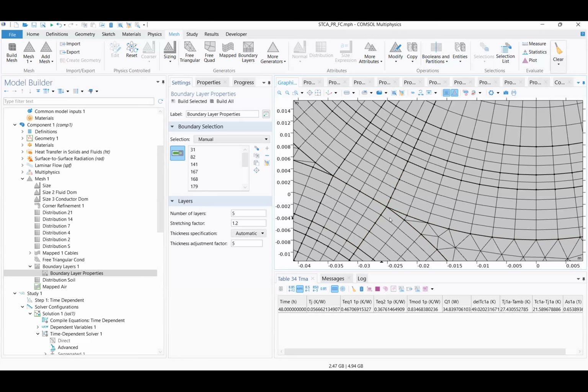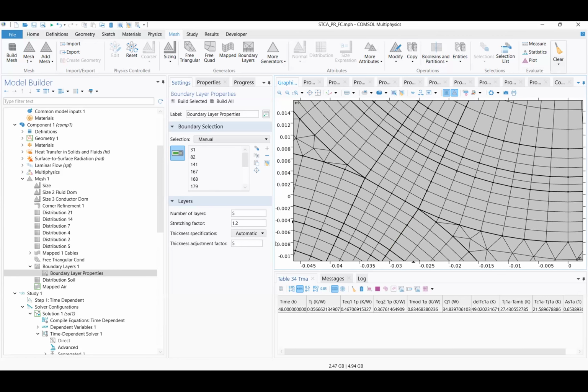So if this area is very small, you're magnifying the error. So instead of having the conductors touching at one point, it's best if we make these round surfaces that should touch each other become a straight line. And then the problems with small area triangles disappear.